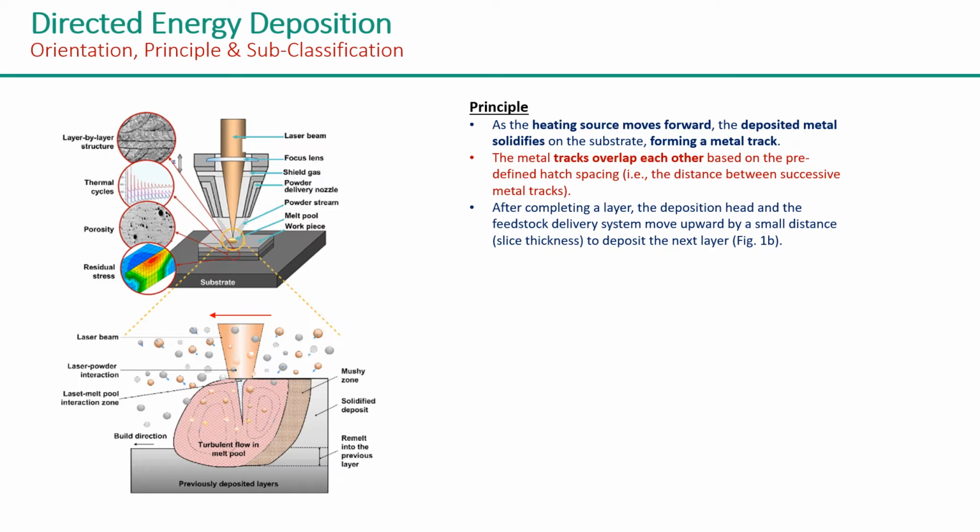It's coming like this, and along with that, from the same nozzle, the material in the form of powder is also coming out, and the laser heat source interacts with the feedstock powder, and it's melted together. And when this whole nozzle moves in a particular direction, in that direction the deposition is formed.